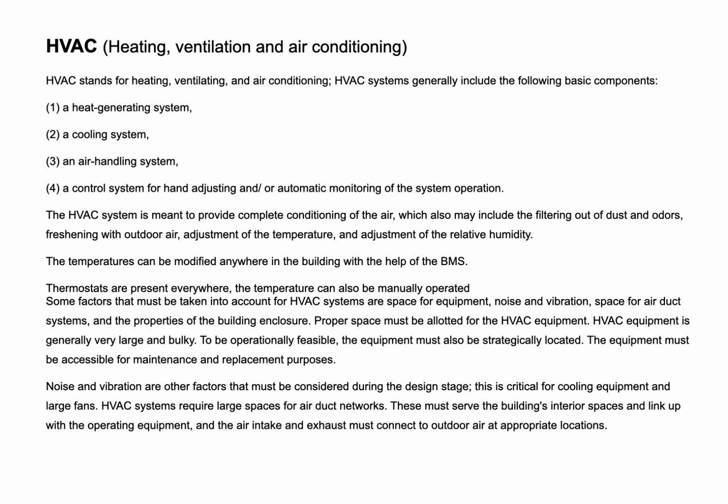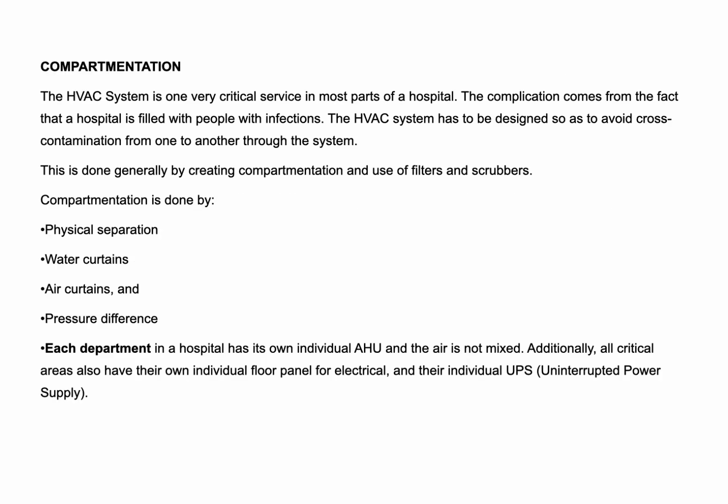HVAC systems require large spaces for air duct networks too. Ducts are used to serve the building interior spaces and link up with the operating equipment. The air intake and exhaust must connect to the outdoor air at appropriate locations. As discussed before, compartmentation is a very important aspect in hospitals. The HVAC system is a very critical service in a hospital.